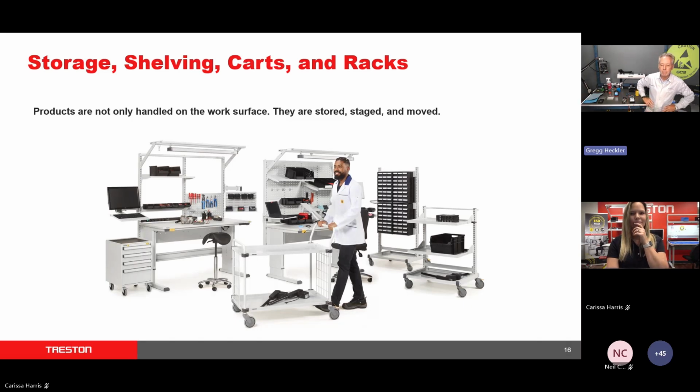Storage is very commonly overlooked. How many times, Greg, do we walk into a facility and there's clear bins sitting there right next to the board? A yellow bin, a blue bin, a red bin. Those are all non-conductive. They're not static dissipative. So again, the young lady says, I got screws and bolts in there. Well, you saw with our demonstration, isolated conductors are a big problem, just as the other static generating materials.